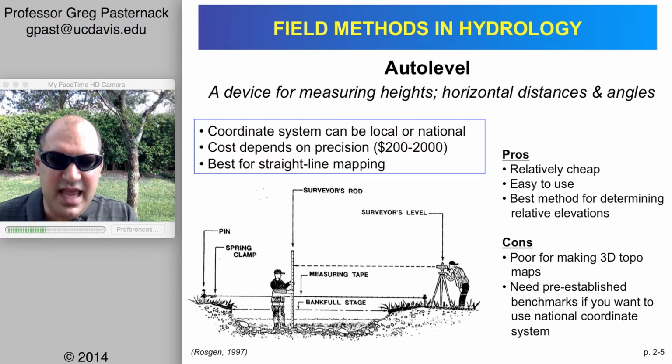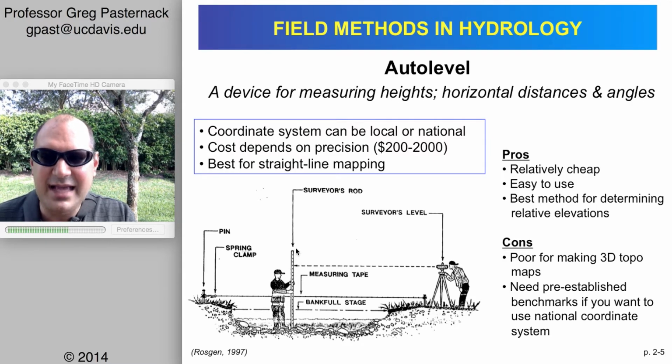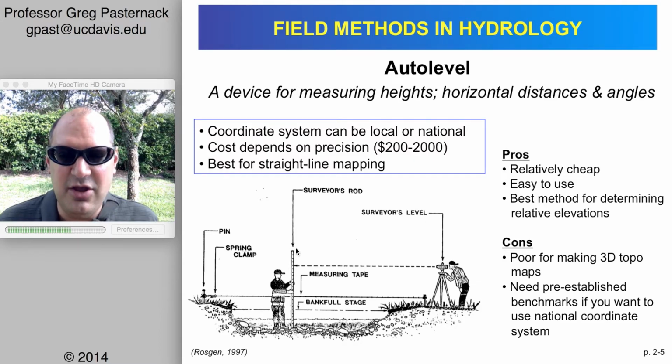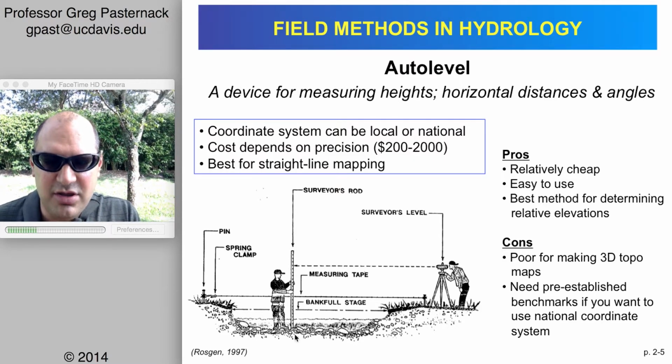You can see in this case where we're on the riverbed, the position is pretty much near the top of the rod. The numbering starts at the bottom, so it goes 0 and then it graduates up to the highest number at the top. What that means, and this is a harder thing to visualize, so this will be something that you can practice in the field, but here the surveyor is at the lowest location in the channel bed, let's say, and the number is going to be a very big number.